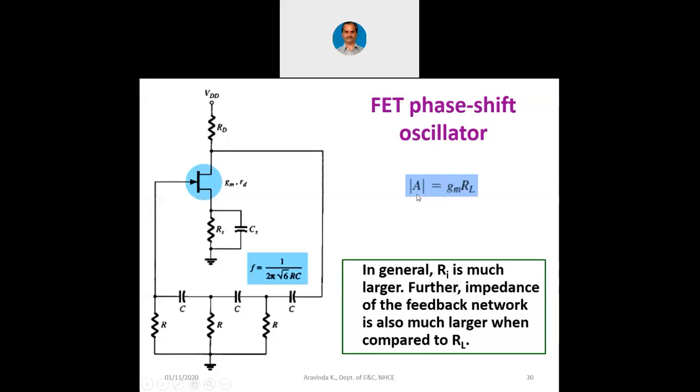Now, we have already performed the AC analysis for the FET circuits in the second module. You will have to recall that now. Here the gain of the circuit is A equals Gm into RL, where Gm is the transconductance. Now this RL can be this small RD we have here within the FET and capital RD we have here in the AC equivalent circuit.